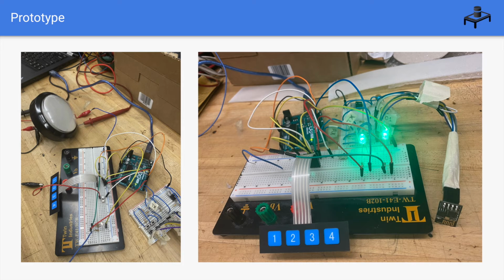This is the first prototype for testing purposes of our project. We used an Arduino Uno board to program the Atmega 328P chip and debug it using the serial monitor. The rest of the components were laid out using a breadboard and jumper wires. For our power supply, we used an AC plug with a built-in AC-DC converter that provided 9 volts DC.